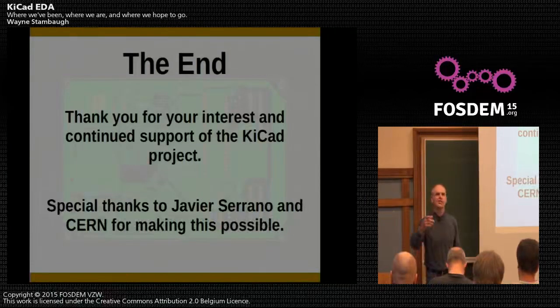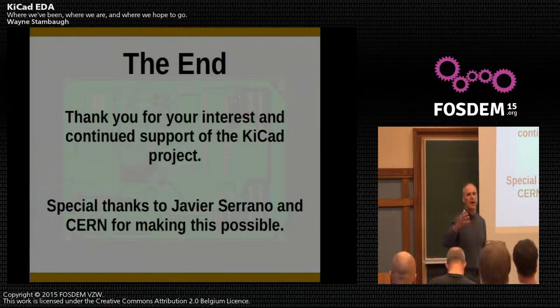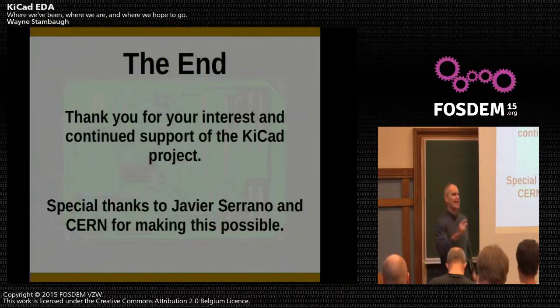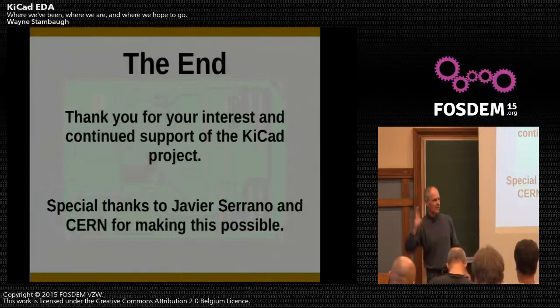Okay, the question is about Eagle import, both libraries and boards, or just the libraries? Well, let me clarify that. Right now, only the footprint libraries and board import are supported, and that's only in the latest file format, which is XML, or like an XML dialect, isn't it? Their newest version 8.